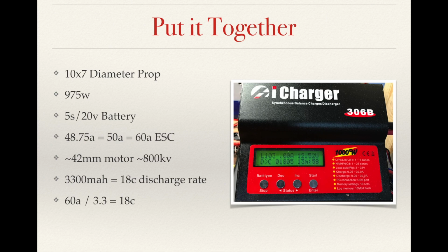And good motor companies will put data points out there telling you with a given prop size, a given voltage, here's what kind of wattage you should expect to draw, and here's the amperage that we saw when we tested the motor given those parameters. So I just happen to know that, for this particular layout, this would be probably a pretty good motor selection for this type of plane given the parameters I've established.